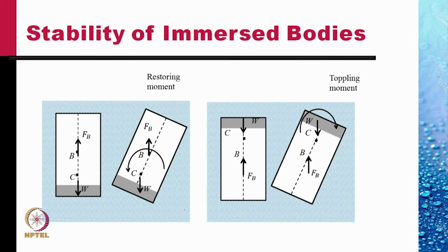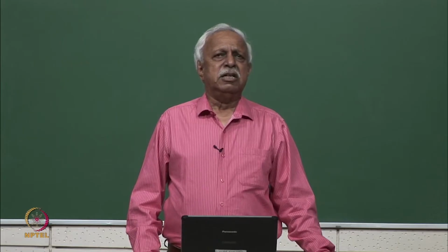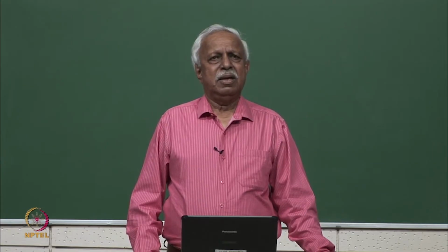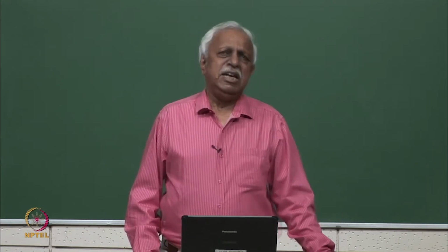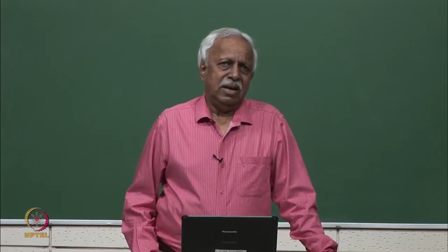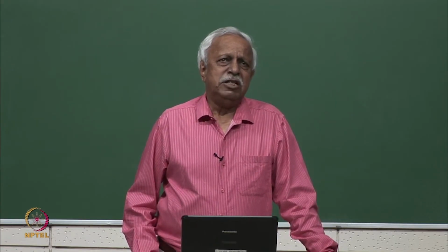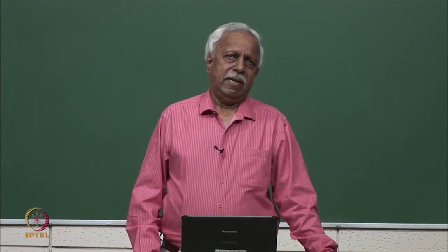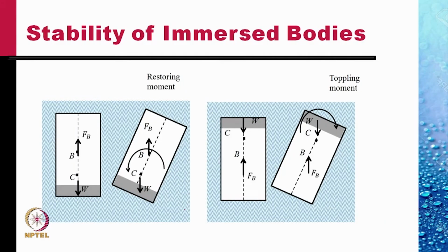But if this body is disturbed slightly so that it's tilting to the right, it is easy to see that the weight and the buoyancy force would now produce a couple, and this couple would have a restoring moment because this moment is counterclockwise, which will tend to upright the body.